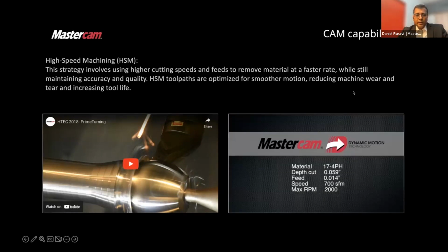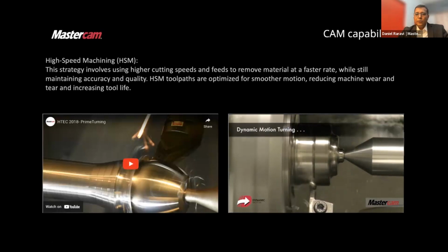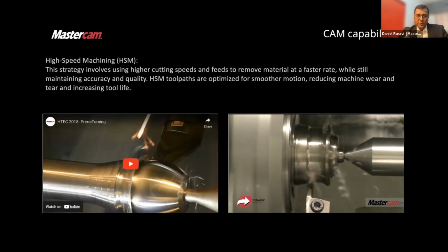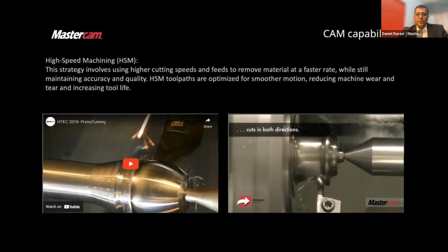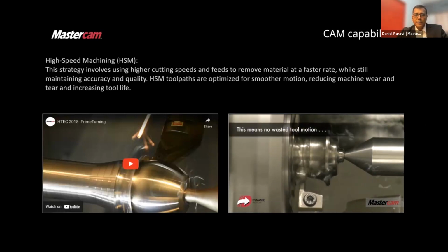Typical 2D turning process is where you have cutting tools which are either left-handed or right-handed, and then you use them to cut unidirectionally. They are unidirectional tools, which means that you can cut only in one direction. But of late, advancements within CAM technology, especially the strategies, allow for the use of innovative tools such as what you see, a round insert, which allows cutting from both sides.